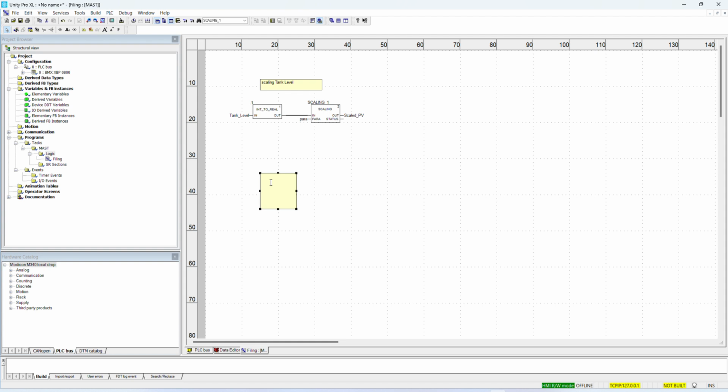And then in this section we're gonna have what you call valve control logic, and put it like that. And then now remember, we're using these levels to control, to open and close this valve. Right, to close, nothing tricky. When we reach 80%, we're closing.